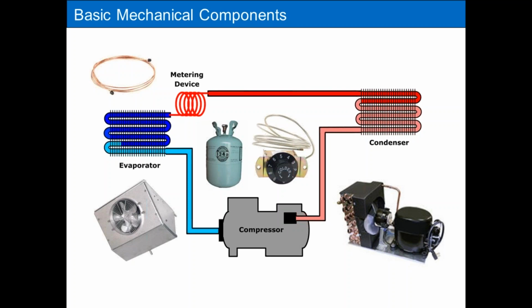We're going to focus on those systems with your cap tube metering devices, so that's a pretty simple type of metering device, but it has its complexity for sure. It has a basic temperature control, but one thing I want to make sure everyone is clear on tonight is that the temperature control we'll be discussing senses coil temperatures, not air temperatures.